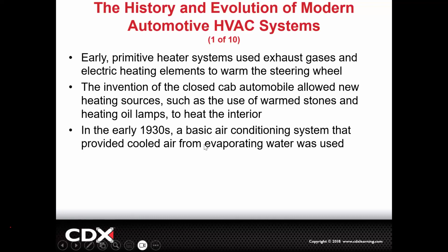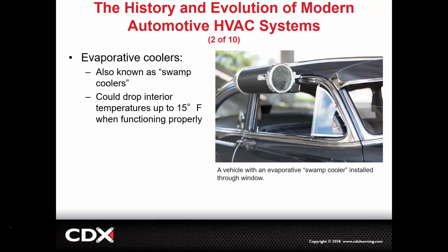There's a slang name for it. Like a swamp cooler. Yeah, swamp cooler. So we'd literally have air come up into this device, and the air would hit here, and right in there we'd have an element that we would get wet. We'd run water to it, and the air coming out of it would blow into the window, and it would actually be cooler because of the evaporation effect.